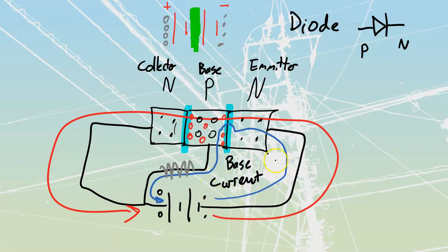If we establish that base current, which is going to be a continuous loss to our system, okay, there's going to be heat caused by this. We are always going to have a little bit of losses applied to our base current, but we are going to be able to have collector to emitter current. But we're going to find that there are more efficient ways than establishing this base current here. And that's what we're going to examine inside of our first set of videos as we get into the actual FETs and IGBTs, because FETs and IGBTs are just going to be us taking PN junctions, and we are going to play with the depletion regions a little more in a different manner to create conduction and blocking.